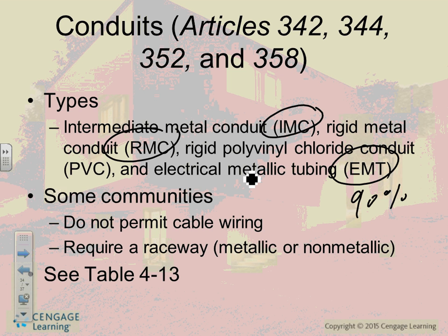What else? Hazardous locations, gas stations. A lot of hazardous locations. Aircraft hangars, gas stations, or anything that has flammable gases or liquids, they use this. So when you think rigid, think really severe physical protection and hazardous location.